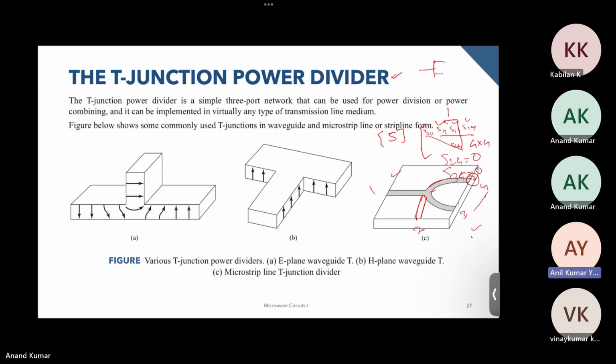I'm following, but I want to know about the case when we try to design a microstrip line. Generally, when we divide with equal power ratio, a 1 to 2 power divider, then we take root 2 times the output impedance Z naught. But when we try to have three output ports, an odd number, then can it be root 3 times, or any other method?